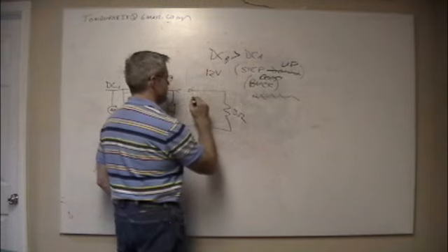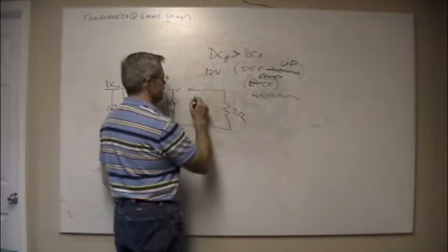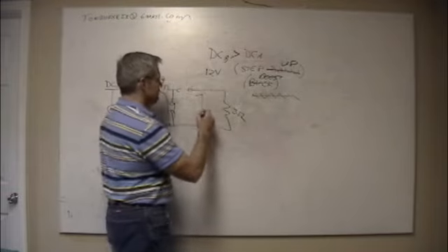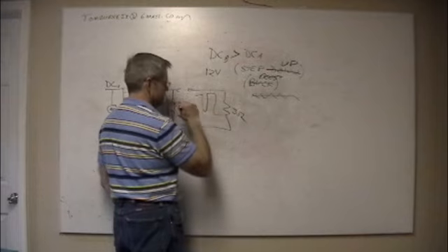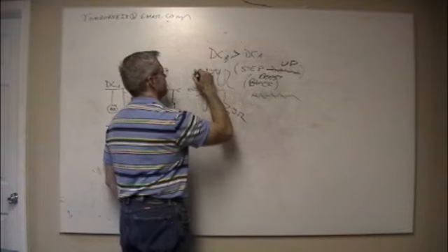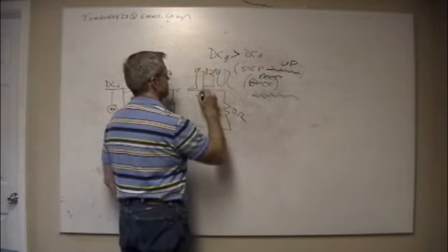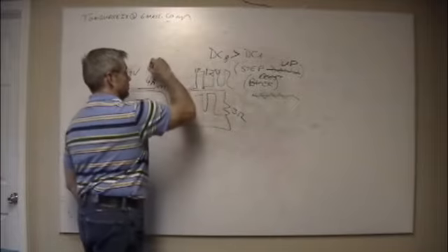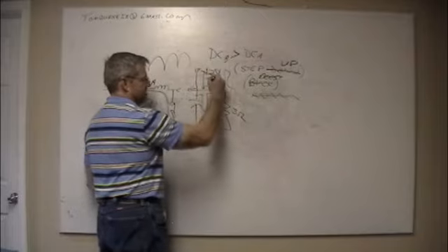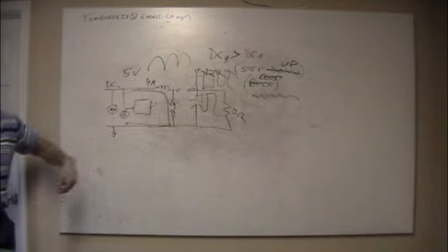And so what you see out here, if I don't put a capacitor there, is a voltage that comes up and then drops away and does this. So I get this weird peaky thing like this, where this is maybe 13 volts and this is 0. Looks a lot like that, right? Now I put a big capacitor here and that smooths that all out. And I start ending up with something that looks like that.